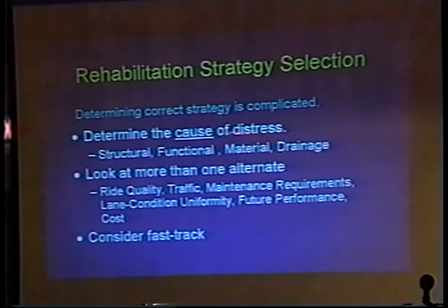If there are material problems, the wrong type of aggregates were used. Back in the old days, we had a lot of D-cracking susceptible aggregates used in our concrete pavements. Since then, we've developed tests to monitor that those aggregates are less susceptible to D-cracking and to frost and freezing damage.